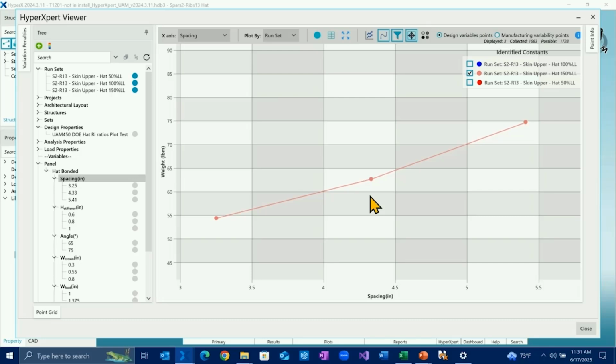So the tool then has the advantage of helping you decide what manufacturing dimensions you want to hold constant, but it also gives you the visibility into the impact of different choices you make in your analysis criteria and trade-offs between how ambitious you want to be with how deep you want to go into post-buckling, and how that would help improve manufacturing by having further spaced stiffeners.